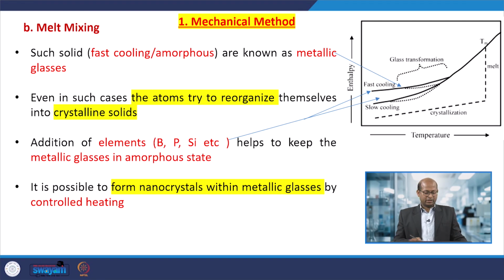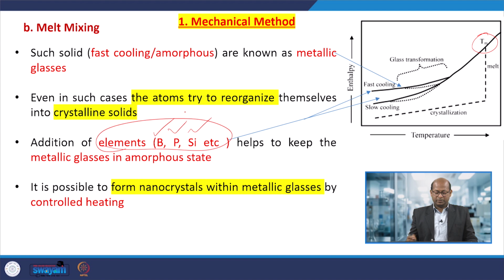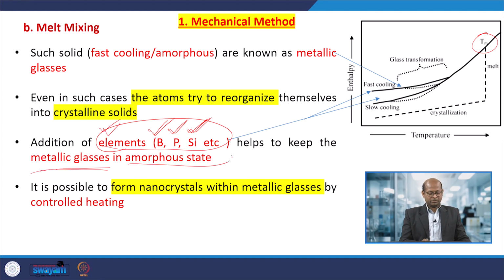So there is also another advantage. When we heat the materials to high temperature and melt them into liquid state, there are other elements also, boron, phosphorus, silicon, that we can mix in, and contaminate depending upon applications. And then if we bring down the temperature, it would assist, when these elements are present, so that amorphous state formation would be much easier.